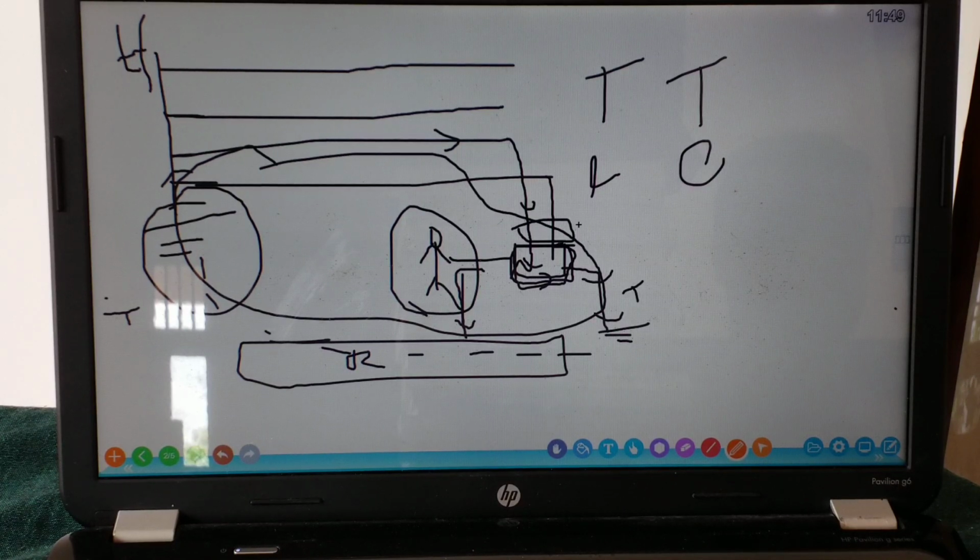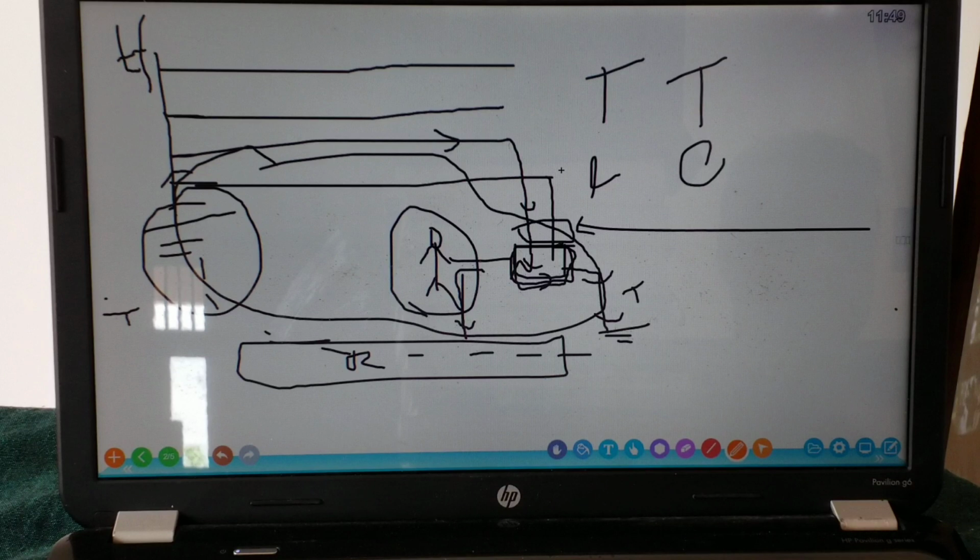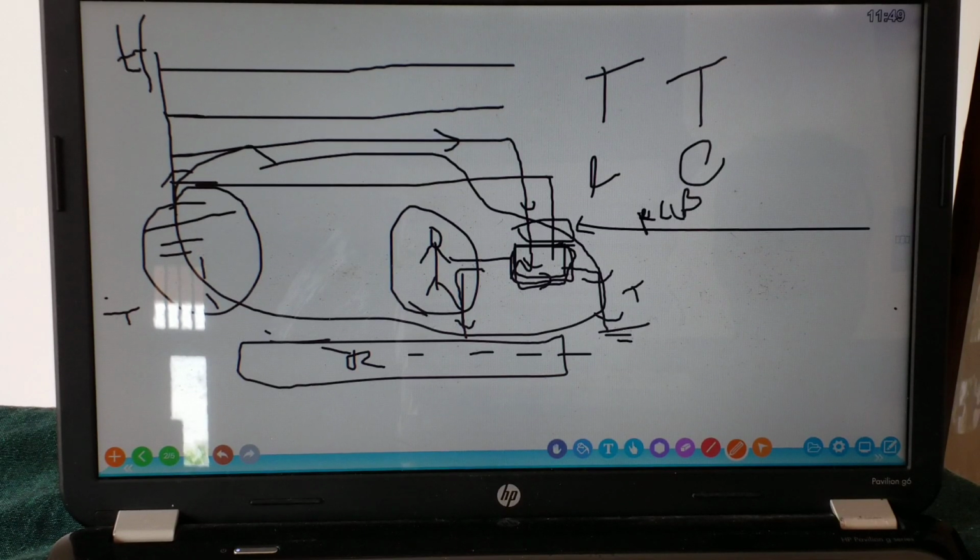There is a leakage, and current will not go to the neutral conductor. So with RCCB we can isolate the fault before it creates major damage.